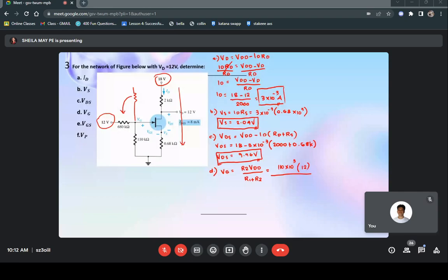Okay, are you following, class? Are you still there? Yes, ma'am. Okay, for VGS, we can do VG minus VS. Okay, VG is 1.67 minus VS, which is 2.04.